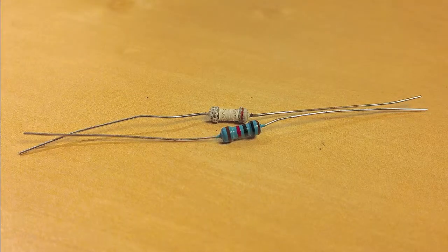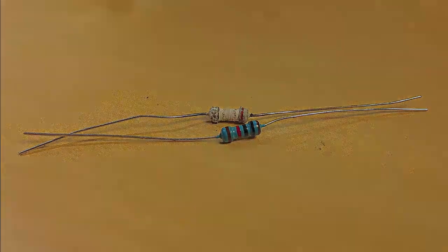So the lesson that we learned here is that a 220 ohm resistor that's rated for a quarter watt power dissipation should not be run with a higher voltage than about 7 volts. If you wanted to pass a higher current through it, so that would mean using a higher voltage on it, then you would have to get a resistor that is rated for a higher power dissipation, so it would look a little bit bigger than this one.